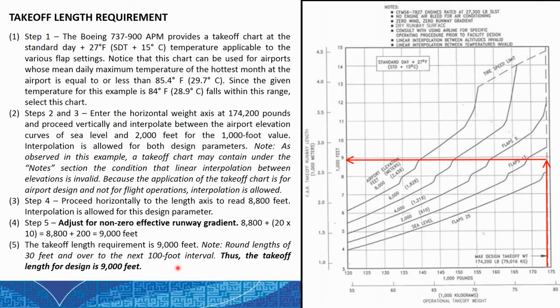Then we compare the landing length requirement and the takeoff length requirement, where the landing length requirement is 6,600 feet and the takeoff length requirement is 9,000 feet. So we will use the takeoff length for the runway length, which is 9,000 feet.